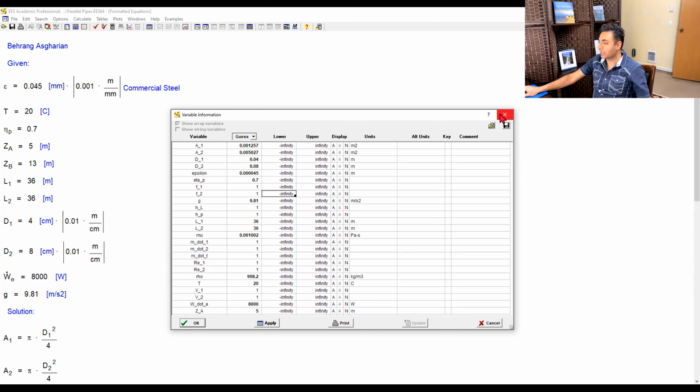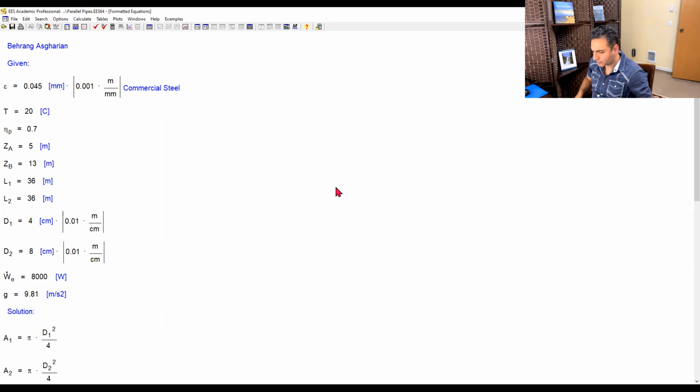That is a technique that can help you in other problems, heat transfer problems, thermodynamics problems, anything that needs iteration, but it needs something, and that's your engineering intuition. Engineering intuition comes from solving a lot of problems before. If you have solved a lot of turbulent problems before for internal flow, the range for the friction factor, in fact, for turbulent flow, is between 0.01 to 0.02, 0.03, 0.04.